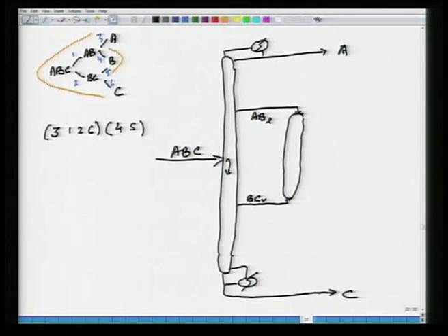And the vapor from here goes out here. The liquid from here goes in here. As I go up in this way, C being the heavy component will not find its way up. There will come a location where I get nearly pure B. Similarly, if I go down, A being the light component cannot find its way down, and I will get richer and richer in B. So, in this small column section, there will be a location somewhere where I have essentially pure B, where I will get a pure B stream. That pure B stream is taken out as a side draw.